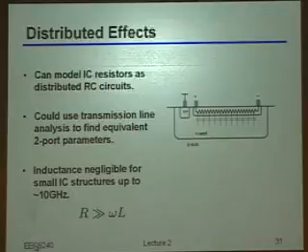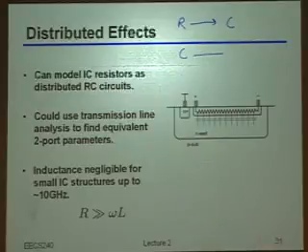Okay, so just maybe really quickly I'll mention a couple of additional things we're going to have to keep in mind, specifically with capacitors, but more generally for all of our passive elements. If you remember, when we talked about resistors, we said that anytime I built a resistor, especially in IC technology, I always also got some capacitance. For example, in those diffusion resistors, I had some extra capacitance from the junctions. Well, similarly, if you build a capacitor, whether you like it or not, you're also going to have some resistance inside of that capacitor.